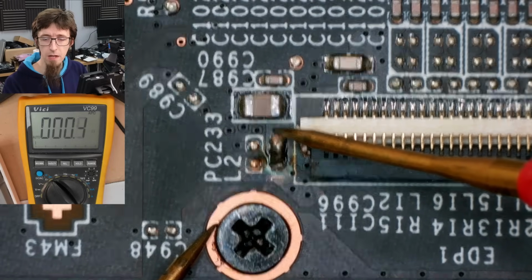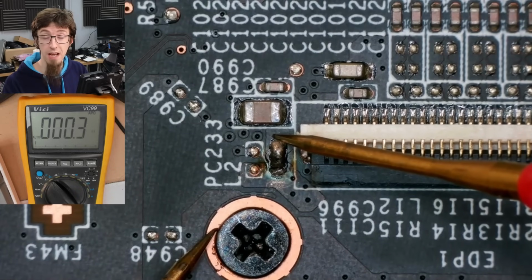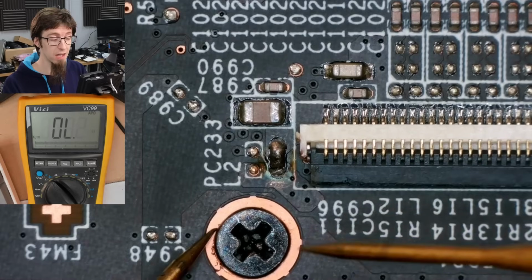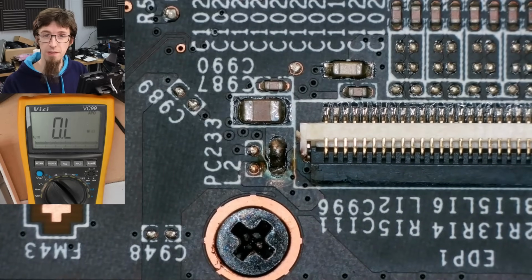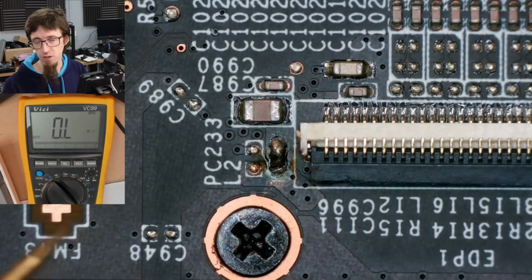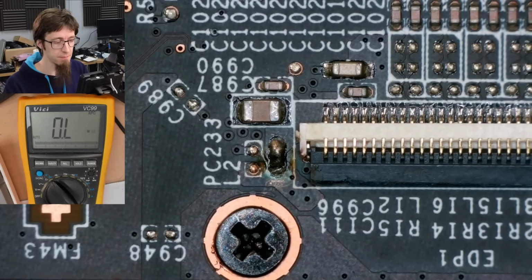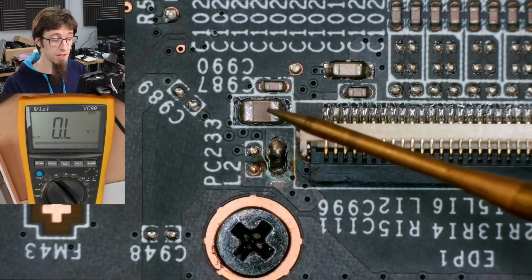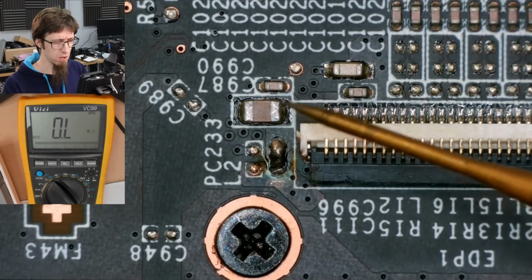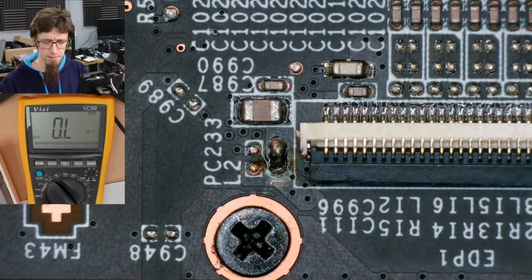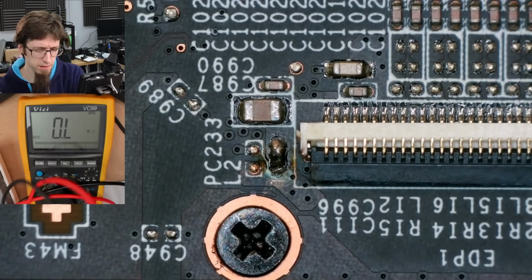Yes, we are. So there's a very good chance that the display is absolutely fine. That's good news. The other news as well is that the customer tells me that there is a picture on the screen, just no backlight. So that also infers to us that the display is probably okay. So the only other two guys that are left are these two capacitors. So what about these guys? Do they look okay? From this angle, they look okay.